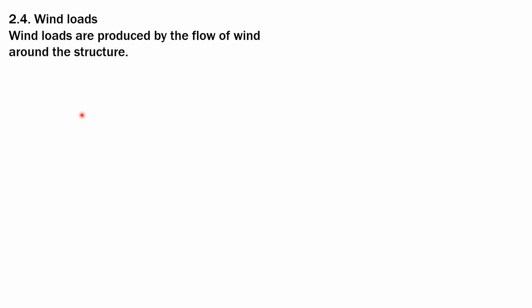It is one half mass times velocity squared, one half m v squared, the kinetic energy, because the volume of wind to be considered is 1 cubic meter, and mass is density times volume. So that's why only the density appears here. This represents the mass for a unit volume of wind flowing. So it is reduced to this.